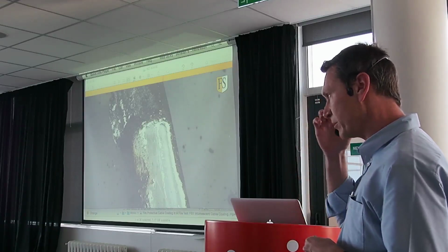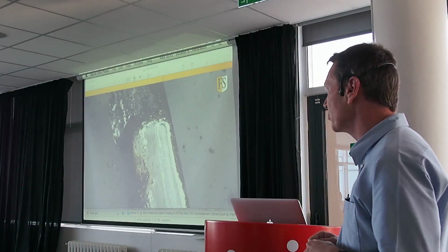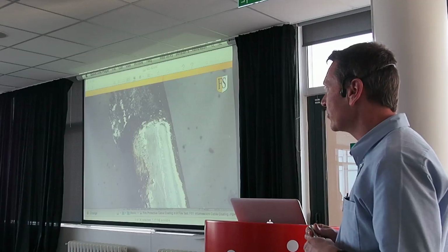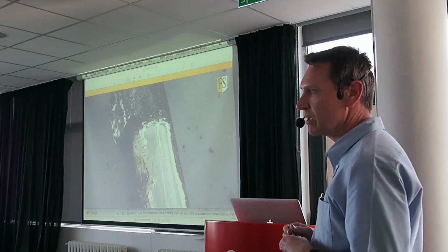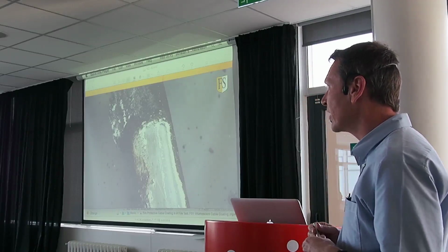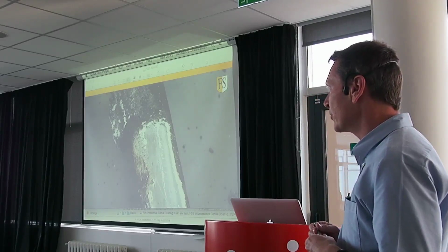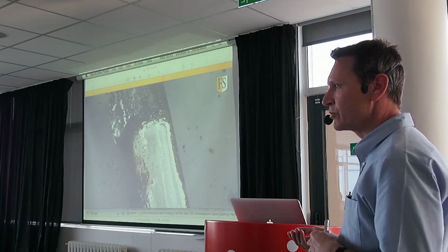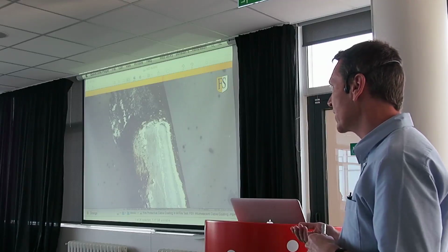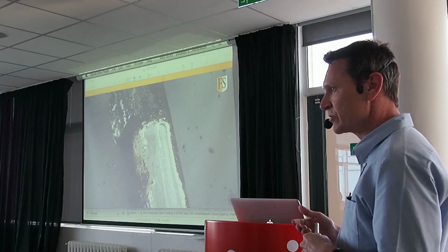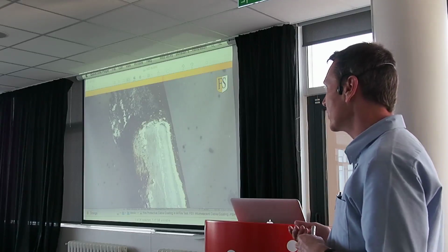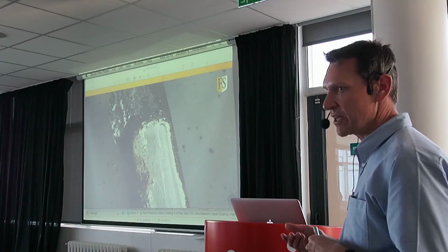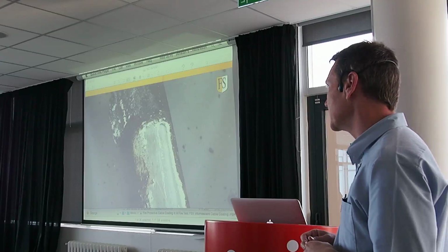We're working on our FS11 now, which is one type of coating to actually be 120-minute fire rated. We think that we'll be looking at around 1.5 millimeters. So you're only looking at a dry weight on an electrical tray of around about 2 kilograms per square metre overall once it's fully cured. So the weight on the tray doesn't exceed the limits of the integrity of the tray and structural capability.